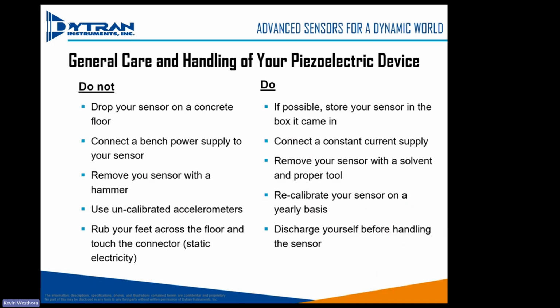So don't drop them. Don't hold them from the cable. Make sure you use a proper power supply. Do not remove your sensor with a hammer. Do not use uncalibrated accelerometers. We recommend that you calibrate once a year. If you do not calibrate locally, we'd be happy to do that for you.